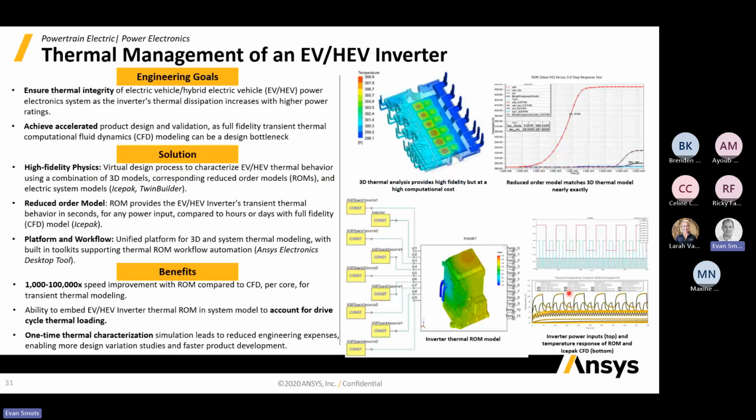Here's an example for thermal management of an electric vehicle inverter. So this is something where we've actually done the 3D analysis of the component, turned that into a thermal model. And in this case, they even went as far as doing a reduced order model as part of a whole power delivery system for the electric vehicle.